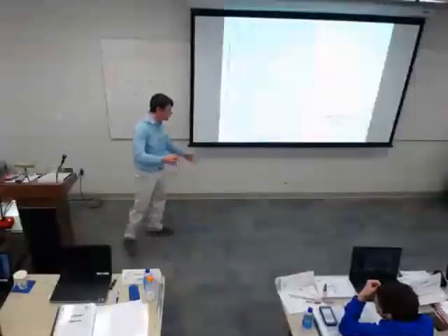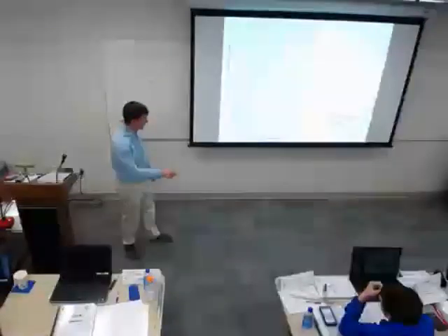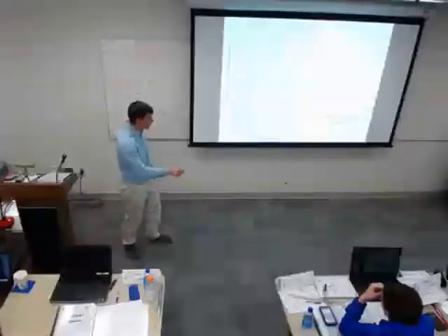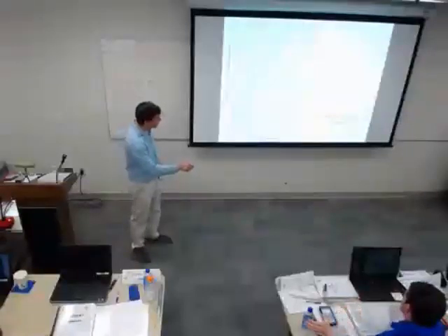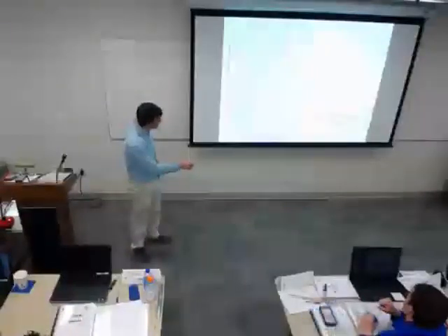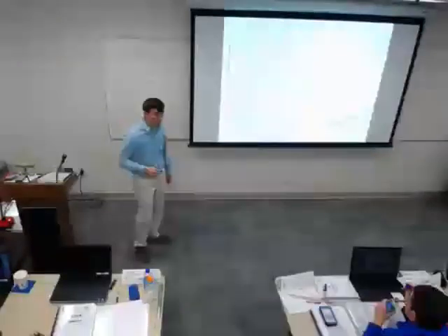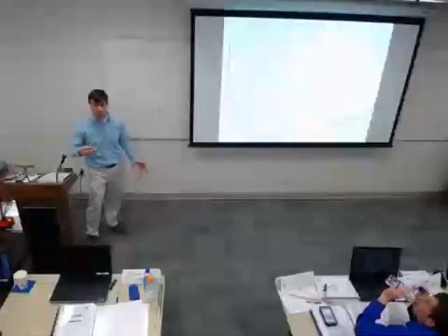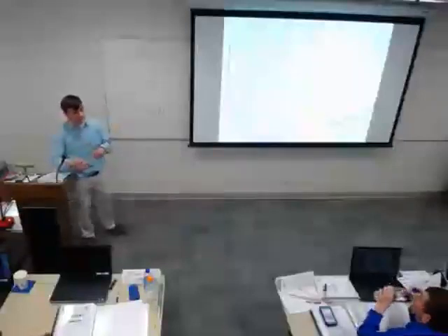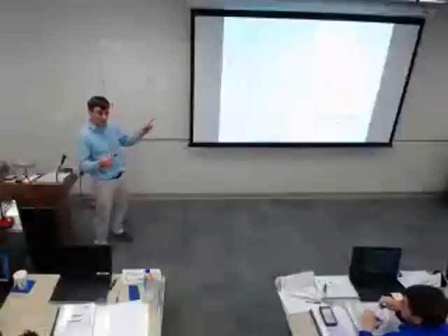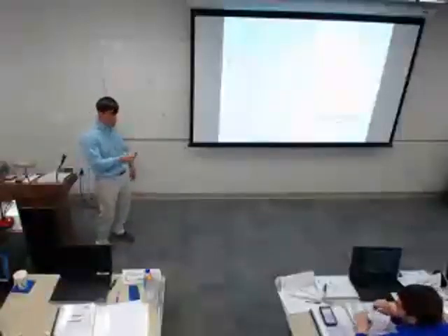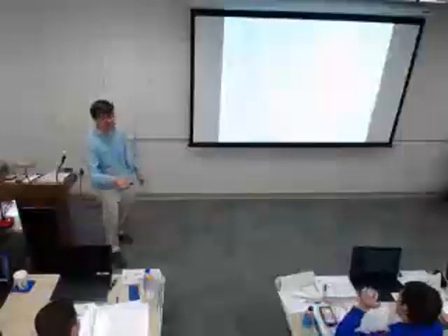I'm going to plot whatever the intersection is of my velocity. I'm going to have to know my velocity. Let's say I'm doing 3,000 feet per minute. Bring that up to my U curve. I would need to account for an extra quarter of an inch or so of static, if those were my physical conditions. Again, this is a design consideration. We're mentioning it though in case you run across a fan that's not doing what it's supposed to. You might want to look and see if you had some of these conditions that might not have been accounted for.